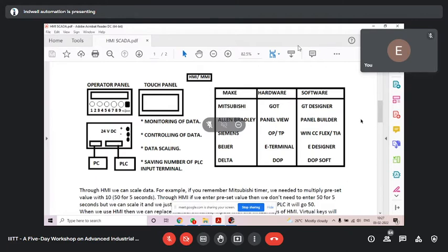We did data scaling. How? Who had answered this? I think Suresh, or I don't remember. Are you present? Can someone tell me why did we divide by 1000? Because this data scaling means what we have done in our PLC in HMI, we can see the same tanks and same control valves and everything how it is operating. That is okay. But can you tell me why did we divide that percentage MW1 by 1000 in Codesys visualization? Because I think our input was in seconds, and PLC gave the output in milliseconds.